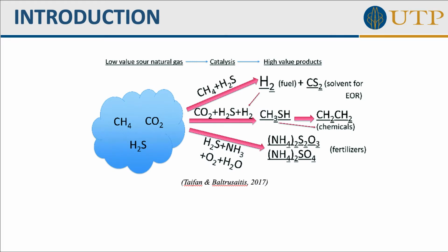Looking into the acidic gases contained, hydrogen sulfide and carbon dioxide have been the major impurities in industrial gas mixtures. The presence of CO2 reduces the energy efficiency of natural gas, and it is one of the top contributors to global warming. H2S, on the other hand, is a highly toxic and corrosive gas. The existence of these acid gases, CO2 and H2S, in the natural gas increases the risk associated with the gas plant and requires the usage of special materials that are able to withstand the corrosive equipment.